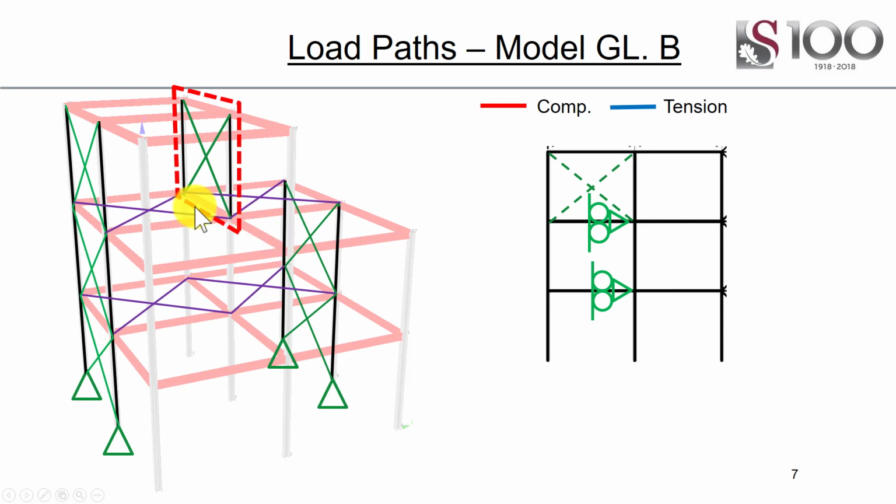If I push horizontally at this position, the relative stiffness of the floor, because of the combined floor and vertical columns, is much higher than this braced bay, a minimum of 5 times higher, but in this case it's much higher than that. That means that relatively speaking it adds a support. If I push horizontally there, almost all the load is transferred horizontally, and it's almost like a giant floor beam or diaphragm, and then vertical brace bays down. So I have supported it laterally.